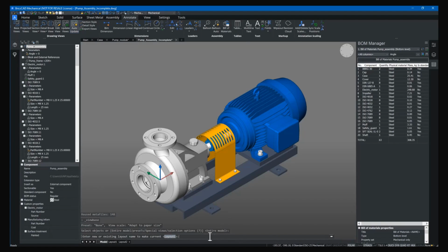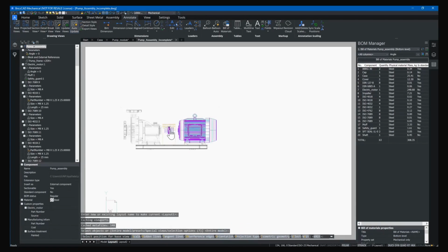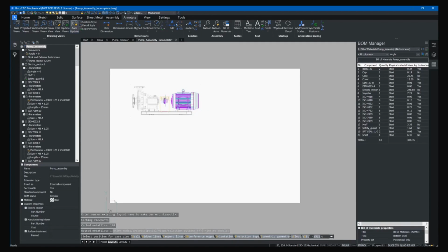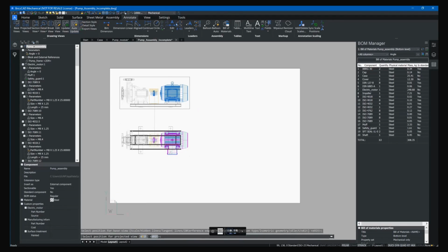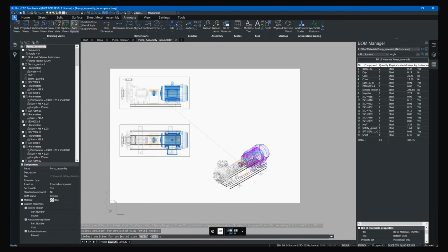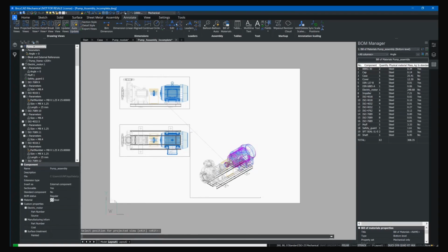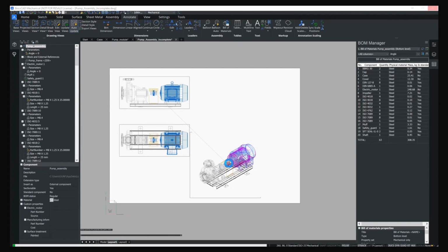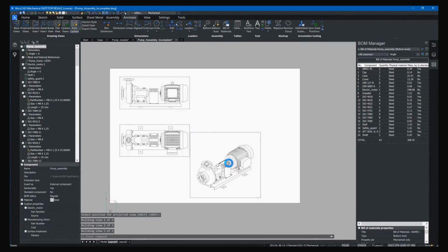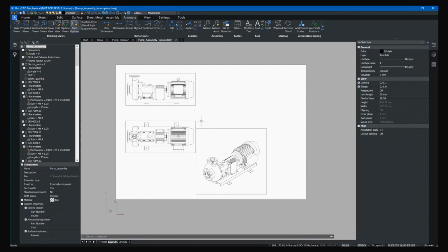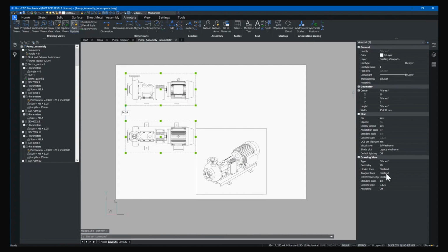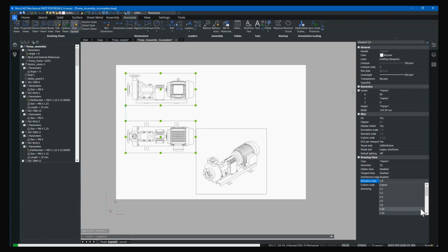And if I go back to the model space, I can generate drawing views from this 3D model. Now I can see this preview of my part. I can select some different views. And when I hit enter, it will start generating these views and turning them into 2D geometries in a sense. I can change the scale of the drawings as well to a standard scale.